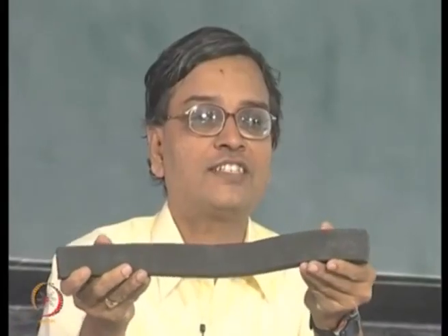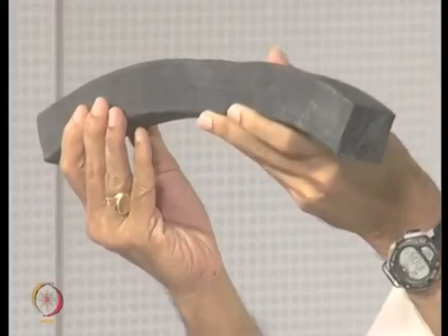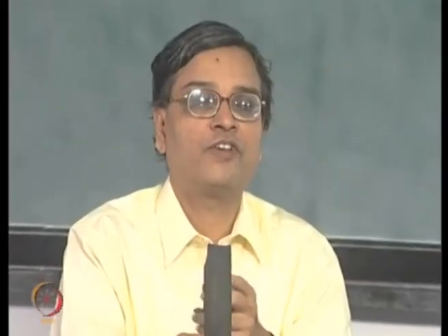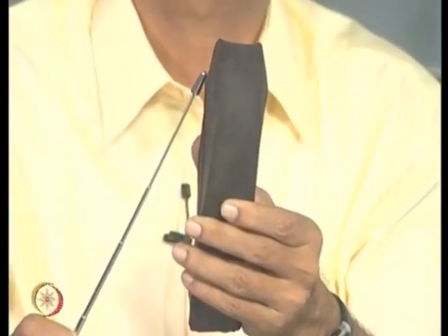And when I go to theory of elasticity, you do not consider it as a line, but you consider that as a 2-dimensional object. But in reality, because you have flexing, the Poisson ratio effect becomes very prominent, and what you find here is, this is the compression side and this is the tension side, and this compression side bulges out because of Poisson ratio effect.